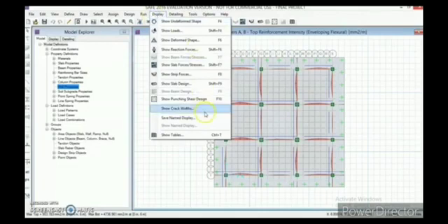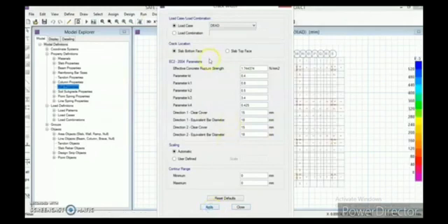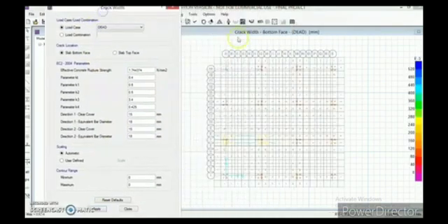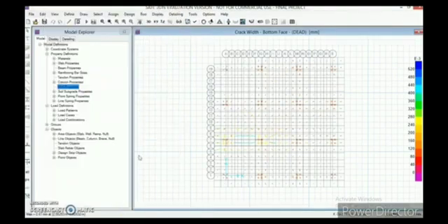So this is how we can also see the crack widths. So apply. So these are the crack widths. We can see different colors, and different colors show different crack widths that might occur on a column or foundation. You can see all of them are very minute, in mm. Yeah, it means a perfect foundation. And close that.